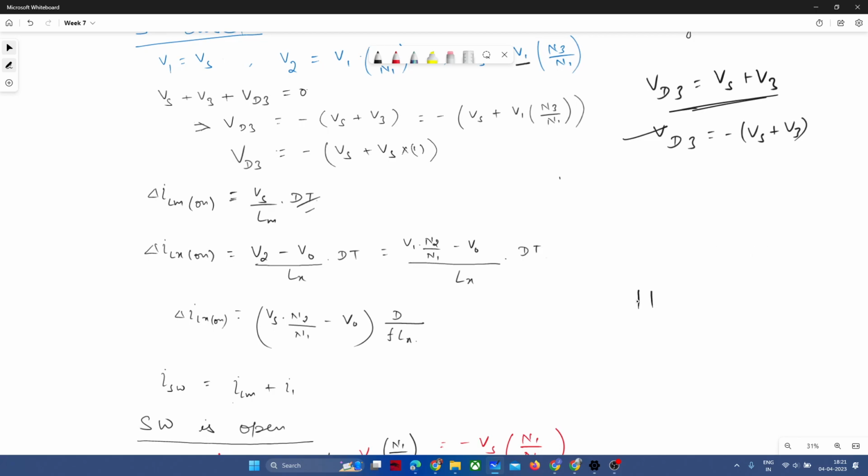As we will see, our field intensity H is equal to Ni by L. So you will require higher field intensity from the supply, and that will be supplied either by increasing the number of turns or increasing the current, if the length of the core is fixed. That we will see in the magnetic circuit section. Okay, sir. This N increases mass and this I increases loss.